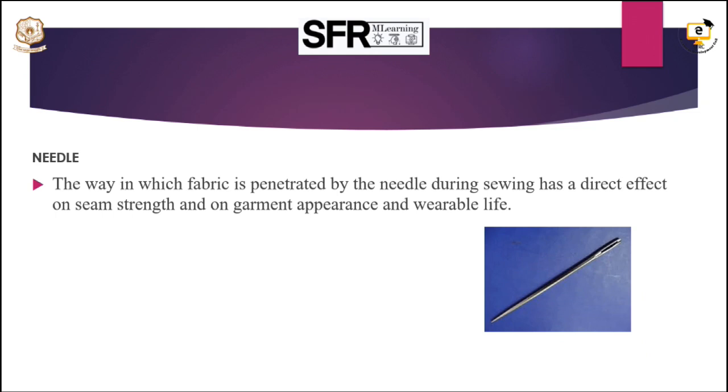And then machine sewing needles: round pointed needle, set pointed needle, ball pointed needle. Round type is the normal machine needle; set pointed means one side is flat and the other side is circular. So this is for the normal sewing machine. And then the flat surface is for power machine needles. Cutting pointed needle, heavy set pointed. Cutting pointed needle means a heavy type of needle.